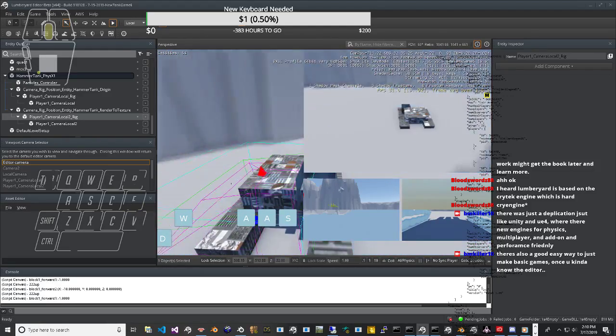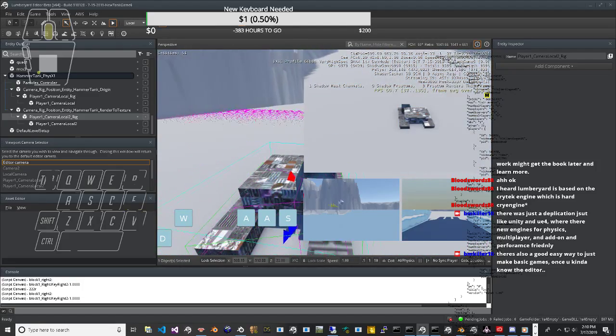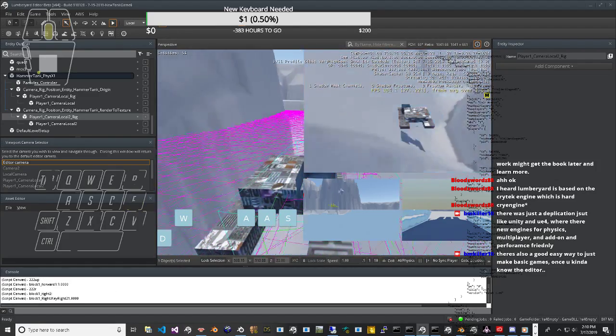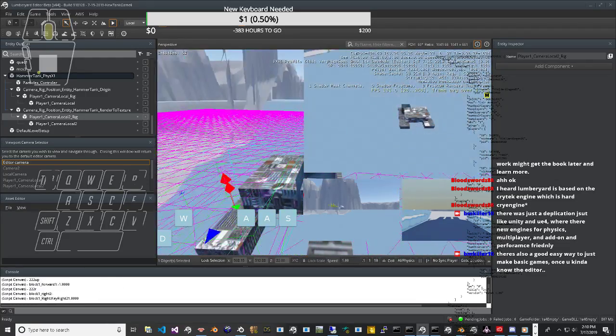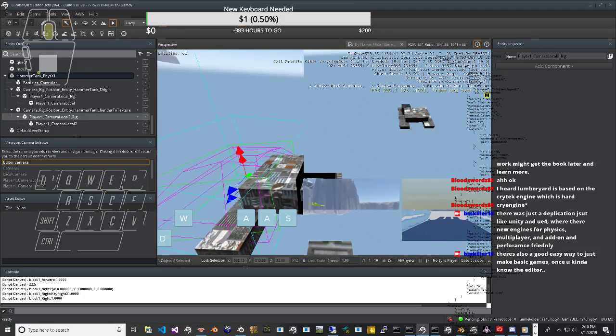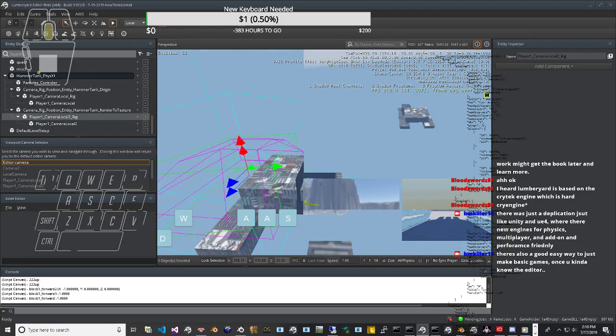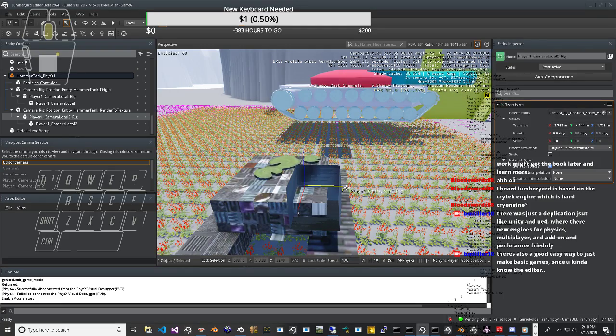This means that it has speed 0 with respect to the ground at that point. The average of the tangential velocities around the wheel defines the effective radius, ρ, as follows. Let θ measure the angular position from 0 to 2π around the wheel. Suppose we knew the tangential velocity with respect to the hub center, v, at every θ.